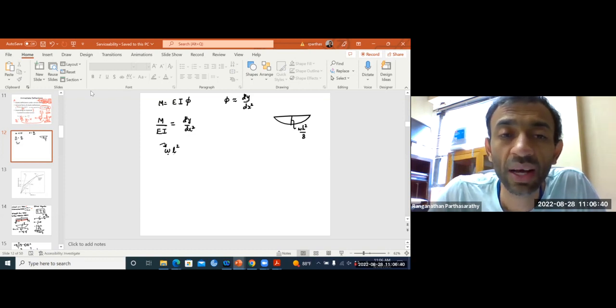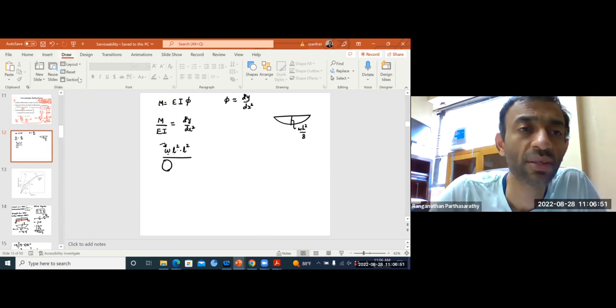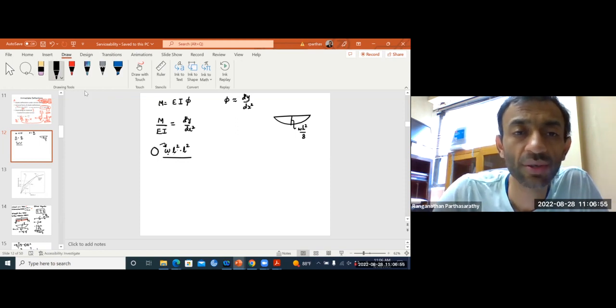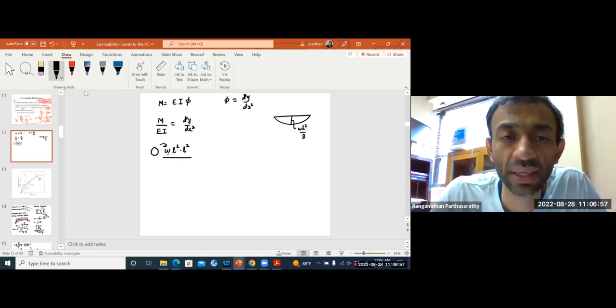So your moment will have a W and L square term. Then you integrate twice, you will end up with another L square term, and then you will have some factor, some number here, and then you will have an EI here.